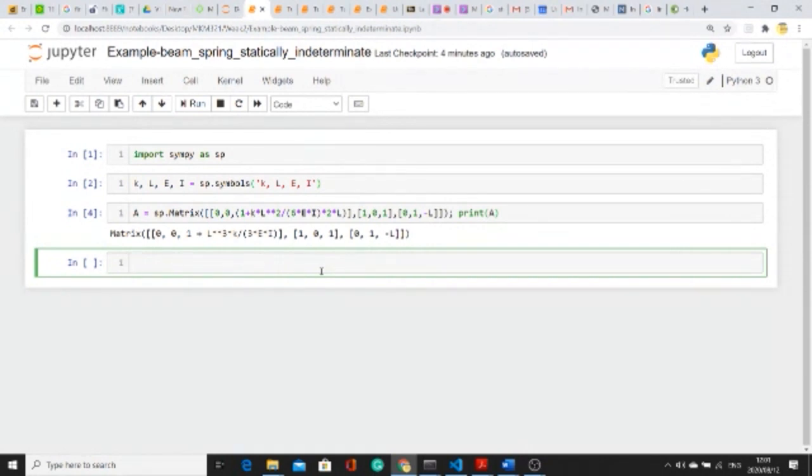And I'm going to hammer this point again, and the reason for that in this course is, if you think about what a finite element package is, a finite element package is a thing that supplies solutions. So you define the problem, you set up the problem, you apply the loadings and boundary conditions, and you clap your fingers, you press a button, boom, solve. What you're confronted with is a solution. What you as an engineer have to decide is, do I trust that solution? And that's why I'm driving this course in that mode.